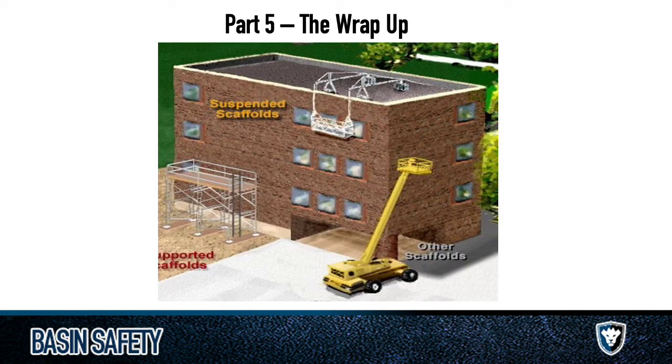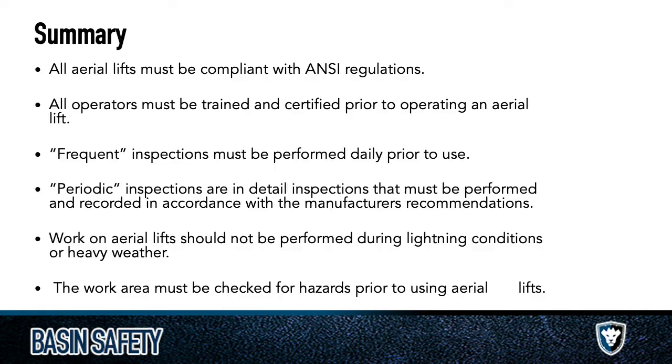So lastly, wrapping this up and summarizing everything. Again, there are a lot of similarities between forklift and aerial lift inspections, keeping the load low and slow, and watching out for people around you. But wrapping up the aerial lifts here, all aerial lifts do have to be compliant with ANSI. So that's one slight difference from forklifts. Forklifts do also follow ANSI regulations, don't get me wrong, but man lifts really tie into ANSI regulations. So remember that ANSI term, that is going to be important.